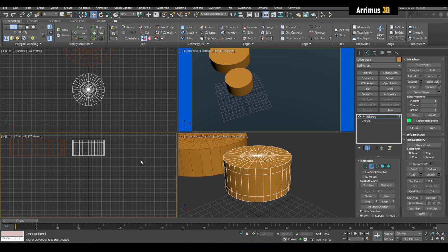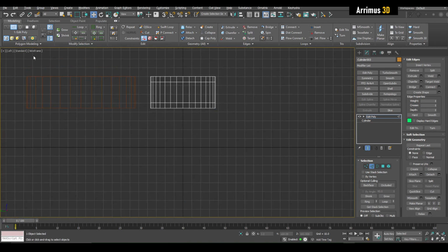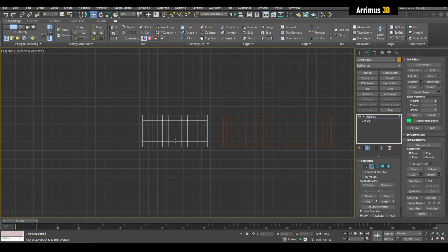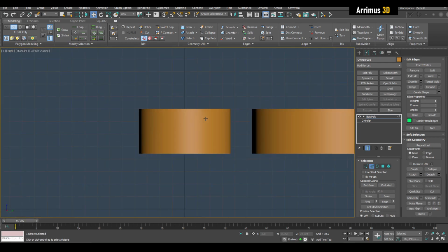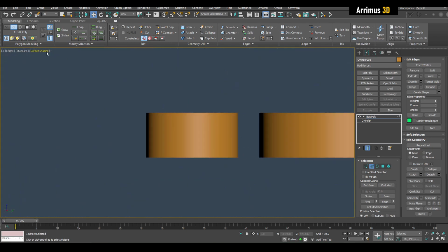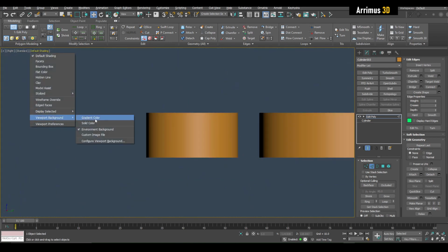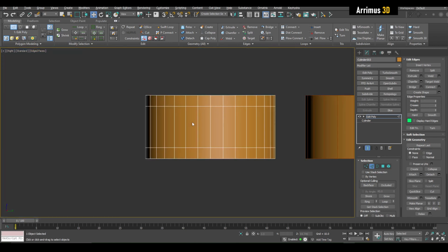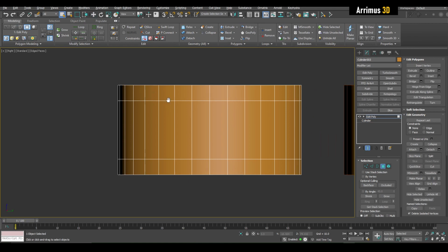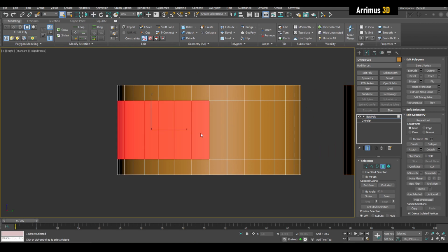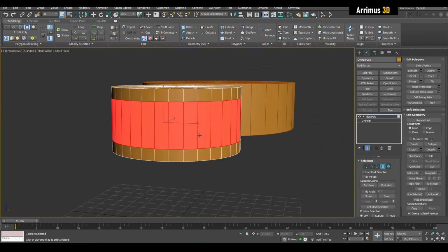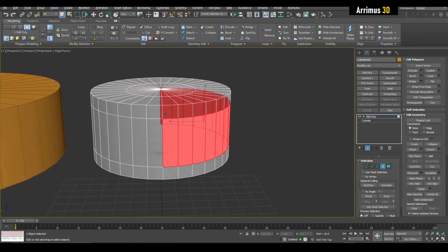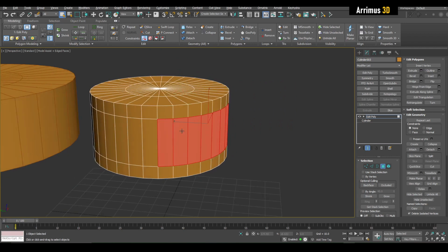Then I will approach this from, let's say, the left viewport, but I will switch this to the right. And you can press F3 to get rid of the wireframes, and G, turn off the grid. The reason it's blue here is that we can just switch this to solid color. And press F4 to turn on wireframe mode. Alright, so I can, for example, select this. The driver will sit somewhere in here. There will be a door somewhere. So I'm going to go ahead and deselect that.